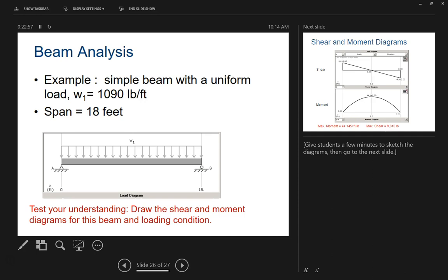But you'll see in the next unit, or the next activity, when we start actually planning out the sizes of beams, that there's so much leeway in there. We're looking for a beam that has a maximum moment of 45,000 pounds. We might get a steel I-beam whose maximum moment is 10% more than that, and there's absolutely no risk that it's going to shear off at that point. Or, like I said before, if we're building it for a school, the safety factor goes up to like 3 times the amount. So we might have a beam whose shear size is like 100,000, just because we know it's going to be so much more than what we actually need.